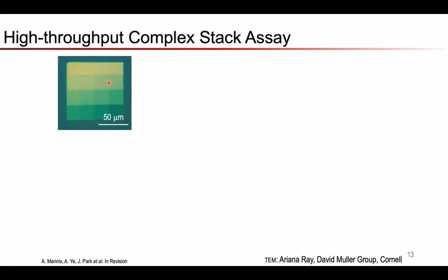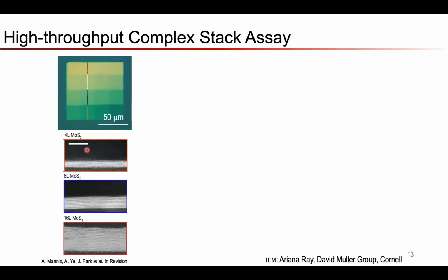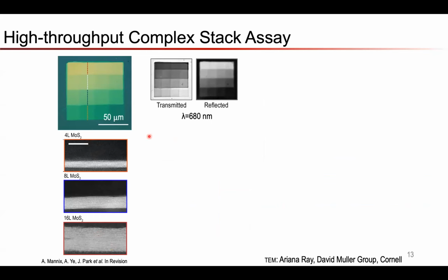And so here's that same heterostructure shown here, and we can use TEM to verify that the thickness is as expected based upon the design of our heterostructure. And we can also use optical techniques to characterize the properties of our film.